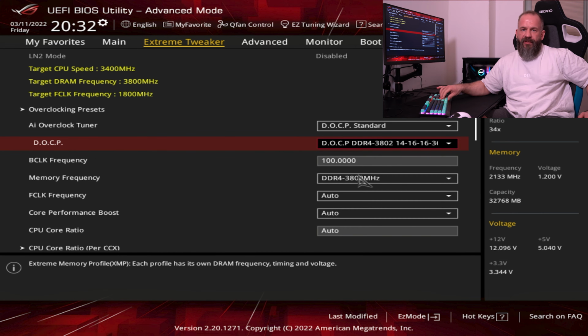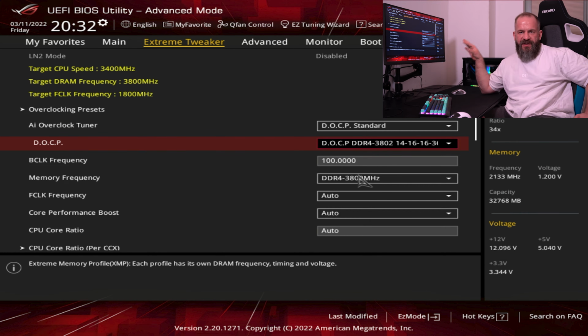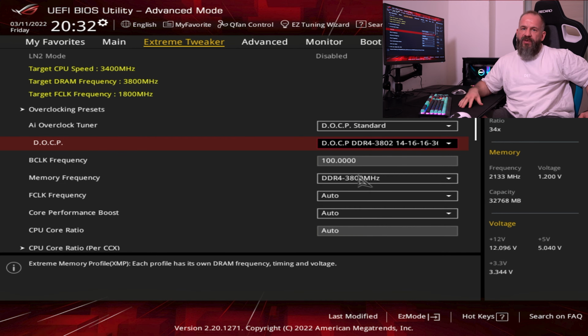They have a different chip for the control and for the management, and also the voltages are a little bit different. I tried it before with the absolutely comparable non-Neo versions. We tried together with my cameraman when we first set up this PC, and they were running poorly. They were not running with DOCP XMP settings because they just crash. They're crashing the whole time. Sometimes your PC doesn't even start. So just keep in mind, if you go G.Skill, take the Neos for your AMD setup.